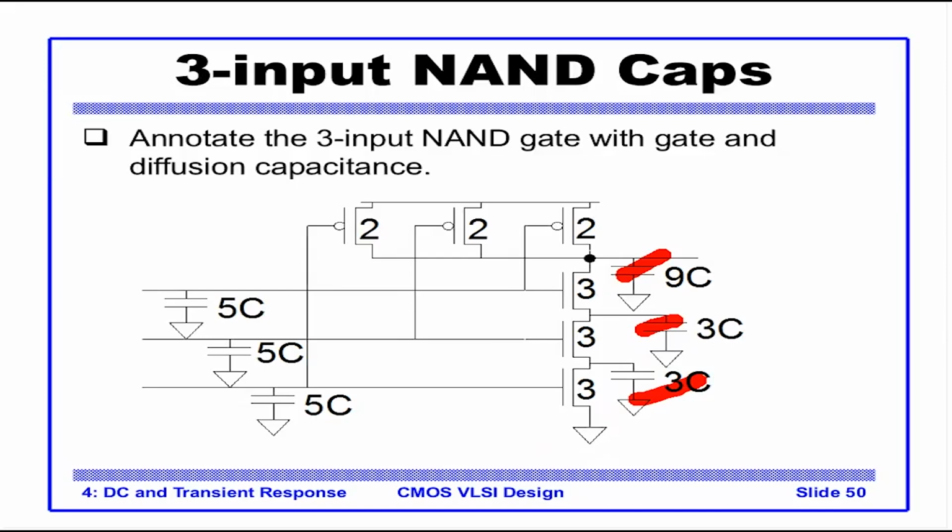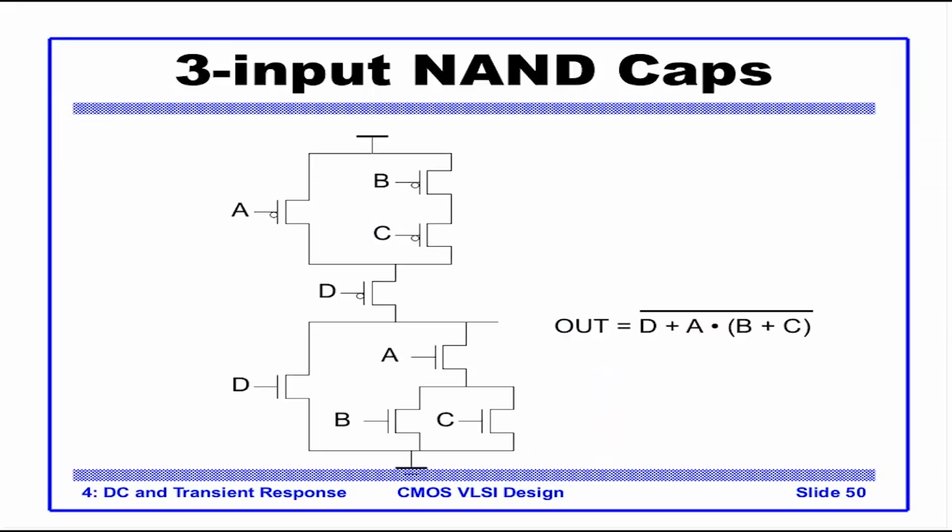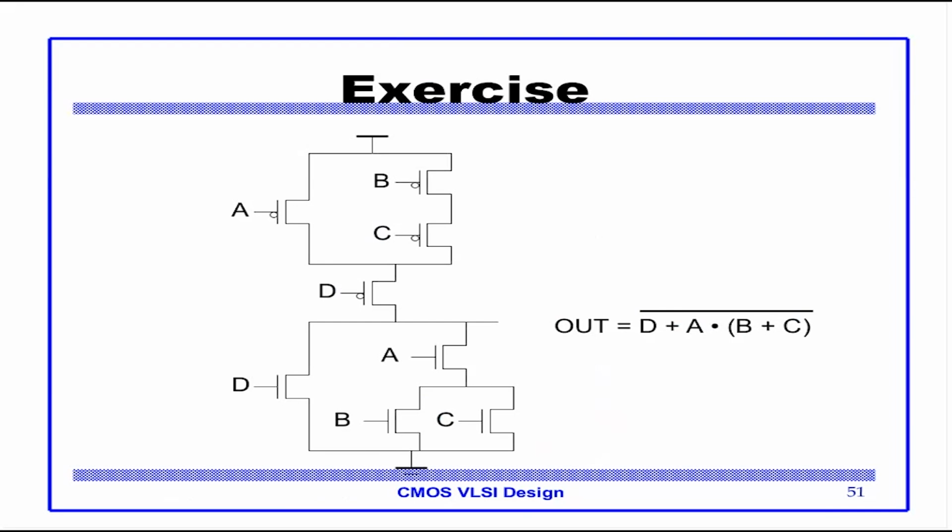Now let's see the delay part. So we have the value of R, we have the value of C. Now this is again an exercise into sizing. Before calculating the delay, the first thing we should do is determine the width of the transistors. Second, we annotate these values there to calculate the capacitance seen by the output, because the delay at the output depends on the output capacitance and resistance, right?